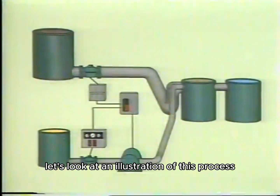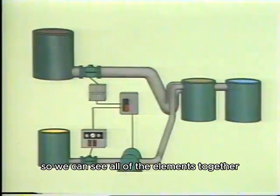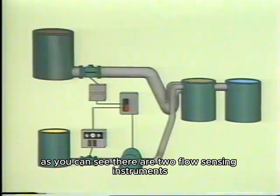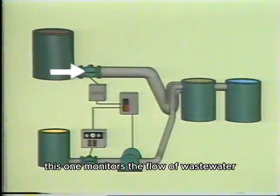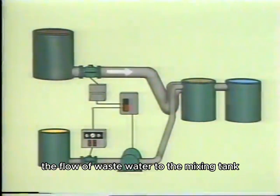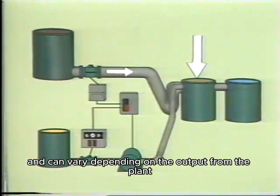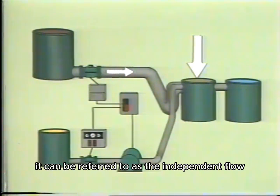Well, now let's look at an illustration of this process and the ratio control loop so we can see all of the elements together. As you can see, there are two flow sensing instruments in this control loop. This one monitors the flow of wastewater that is to be treated. The flow of wastewater to the mixing tank is not controlled and can vary depending on the output from the plant. Since this flow is not manipulated, it can be referred to as the independent flow.